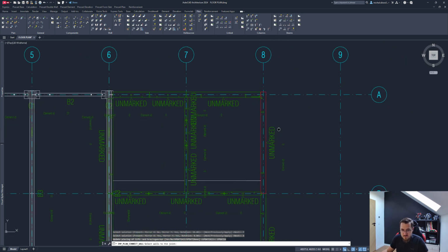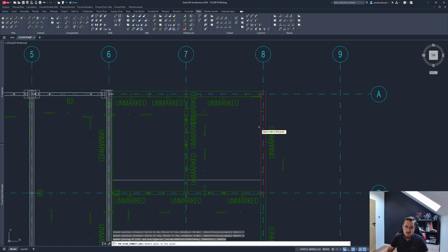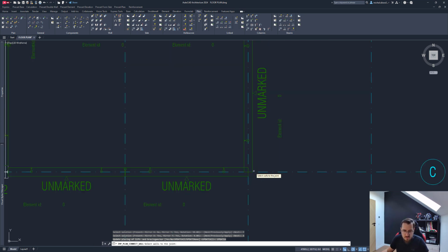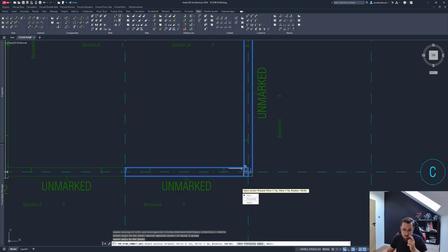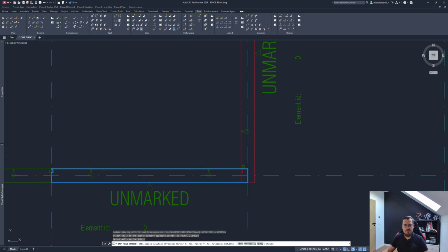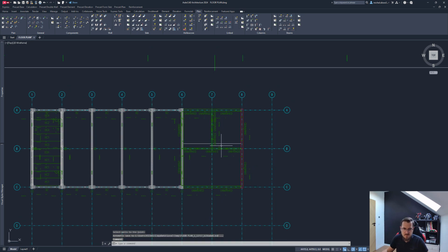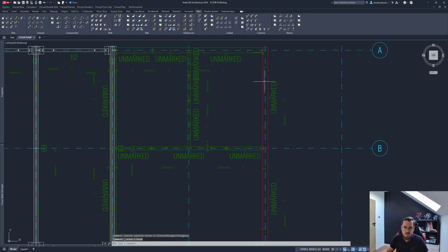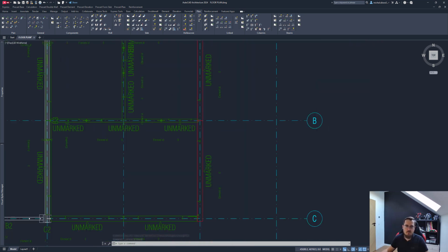What happened now, as you can see, this element got red. It got extended, and it got extended enough that it's too big now to be lifted by the erection crew, or it exceeds our limits in the software. I also select this corner, and I'll apply this particular extension, accept that, remove the auxiliary lines. No worries, we'll split those walls later, or just now, and you will see how easy it is to fix that situation. So this element is too big, fine.